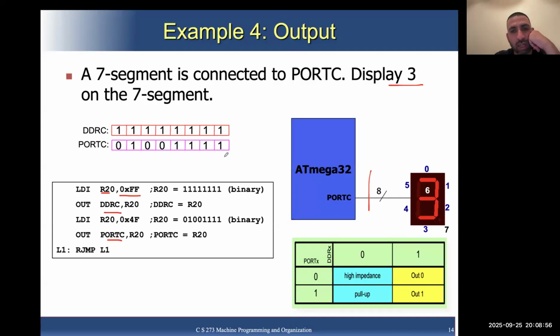So here we are writing to port C in these locations 0, 1, 2, 3, and 4, 5, right? And 6 and 7. So what we are doing is that we are sending one at every place other than these two. And this doesn't matter. Why? Remember we said that port C is 7-bit on ATmega328P, right? So even if it is not, the 7 segment doesn't use the 8th pin. It uses only the first seven lines, right?